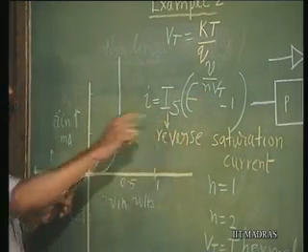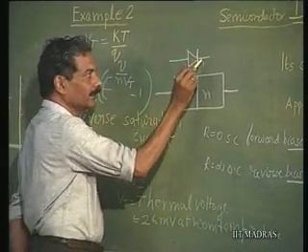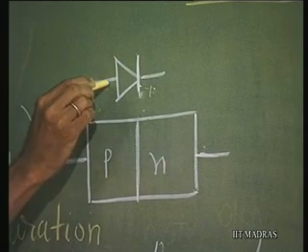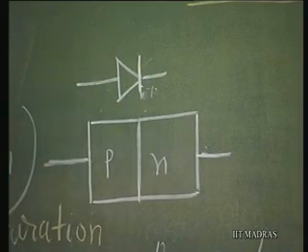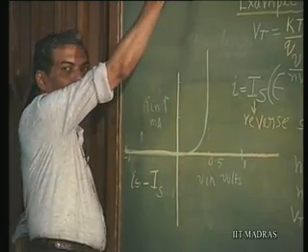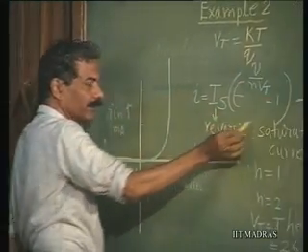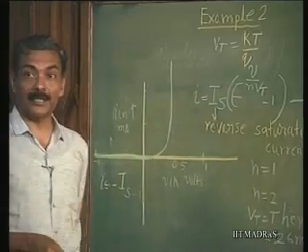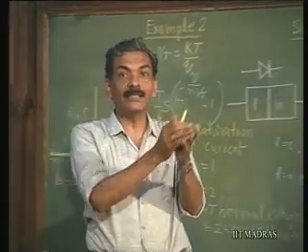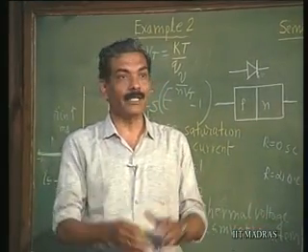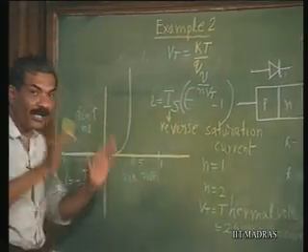In the forward bias region, what is the forward bias region? Let us see. The P side is made positive and the N side is made negative. Then current flow is possible in this direction and it can sustain any amount of current, ideally speaking. So, an ideal semiconductor diode is going to follow this relationship, and a practical semiconductor diode also follows this very closely over several decades of variation in current, all the way from microamperes up to hundreds of milliamperes. This relationship is faithfully reproduced.